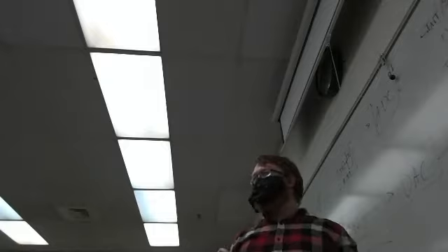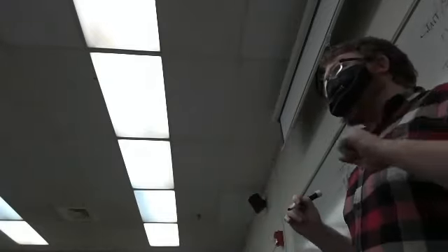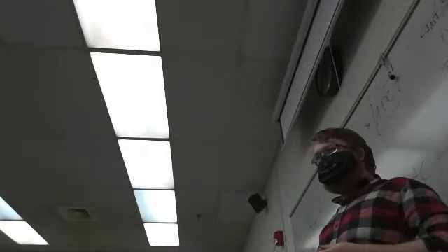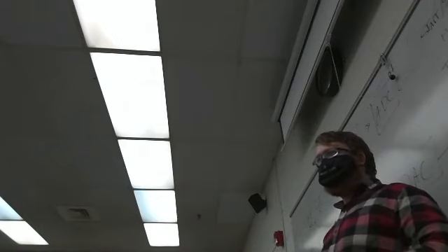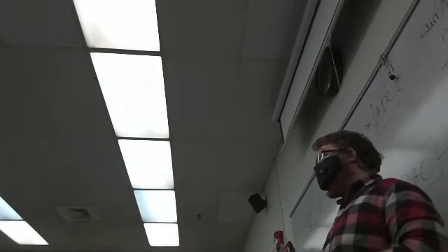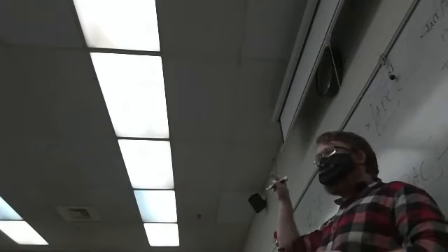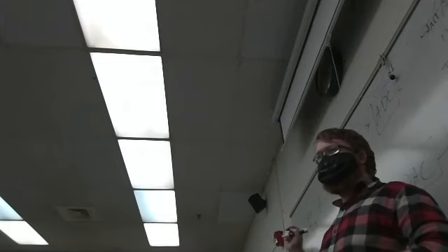How do you record that data over UART? I will actually get to that. We're almost there. Trying to make sure I'm not skipping anything yet, but we may actually be there. Okay, so the easiest way to record data is if you just use PuTTY. You can use logging and it will just save whatever comes back.